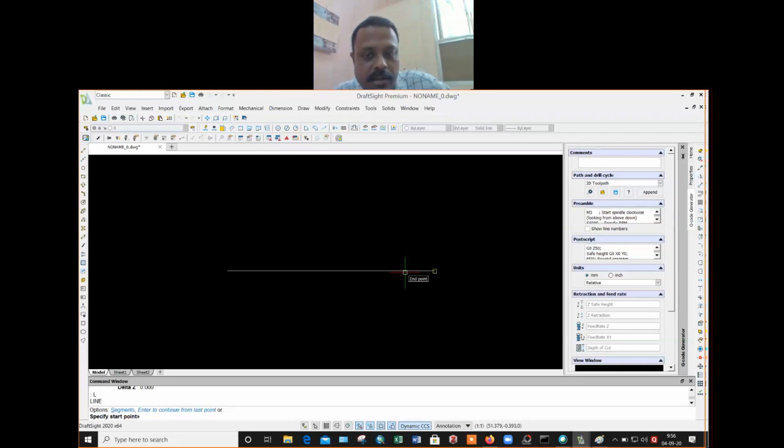Yes, sir. That means my snap is on. I have to switch on my snap. So which key should I press to switch on or switch off my snap? F3. F3, very good. In my case, my snap is on. If my snap is off, you will never be able to exactly pick up the end point. So always remember, snap is very important when you are drawing in CAD. So my first point is the end point of this line. I click here one time.